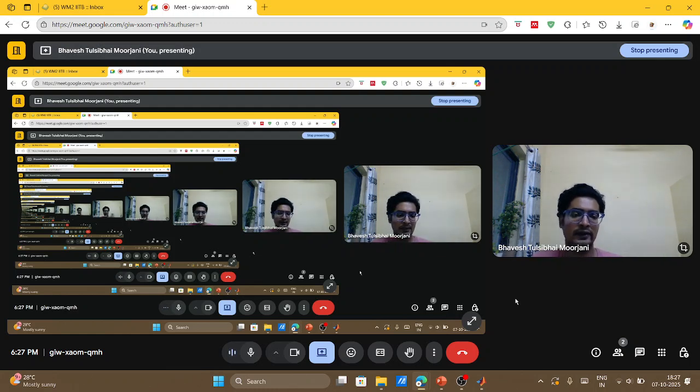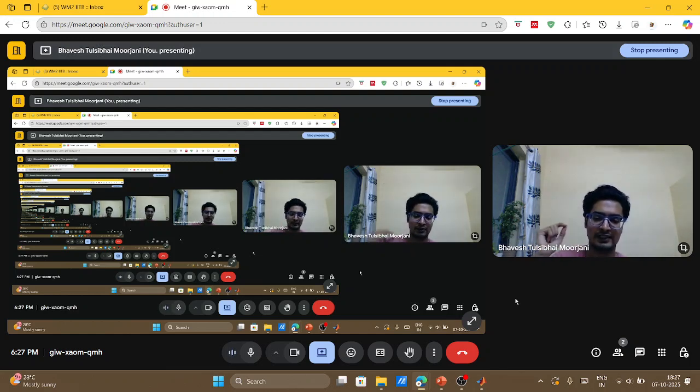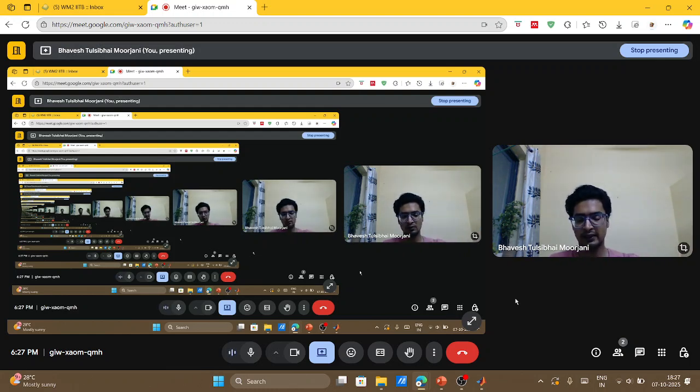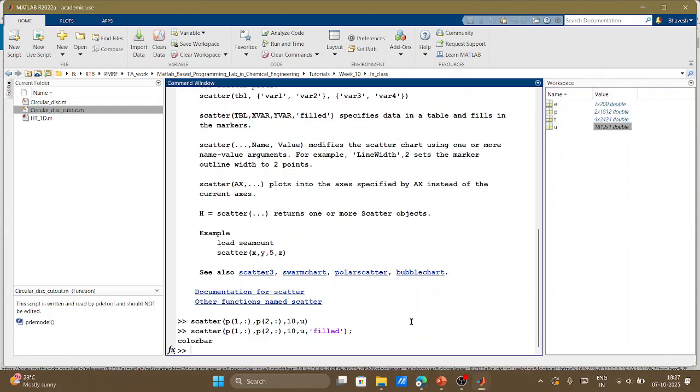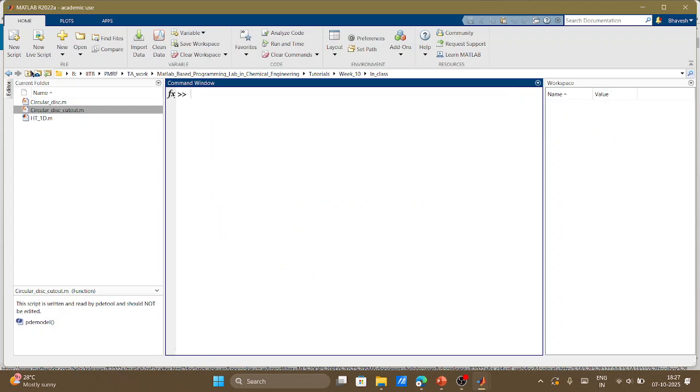So in this case the p matrix represents your xy coordinates, right? Similarly, in other cases also, your p matrix will represent xy coordinates. Let's say I consider the fourth column in the p matrix. That will correspond to the fourth row in the u vector. So corresponding to the fourth column in my p matrix, my data value will be the fourth row of the u vector. This is how you can interpret your data for further post-processing analysis. I had told you that I will show you how to store this data, so this is that part.